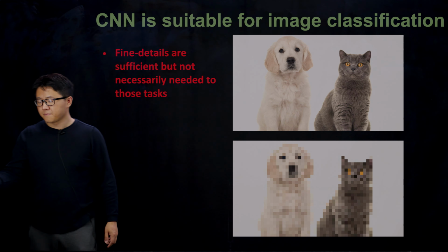So here I'm going to show you an example of shock turbulent boundary layer interactions, where a shock wave comes from here and impinges on the boundary layer right over there, and then reflects back upwards. You can see that there are so many small structures right here near the wall, but above the wall there are only large shock wave structures. In those cases, as you can see, a uniform pixelization is definitely a waste of resources.